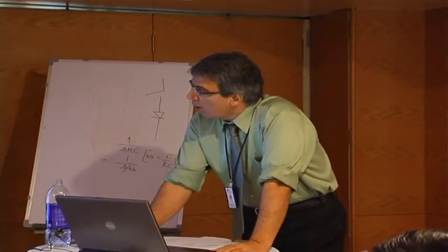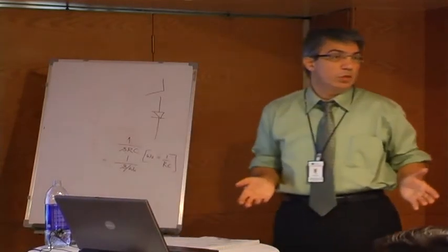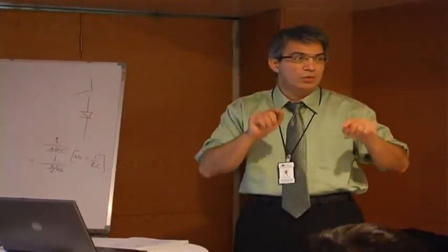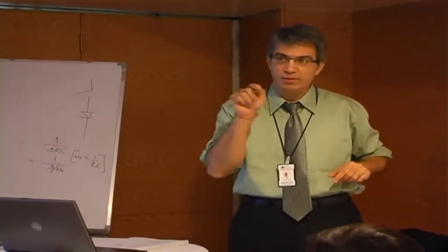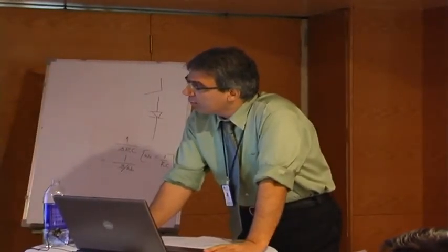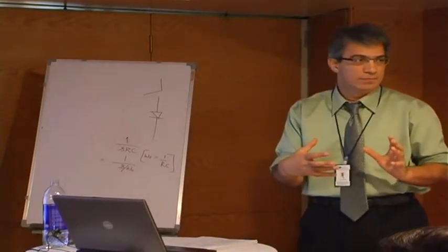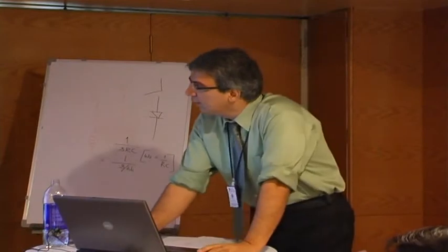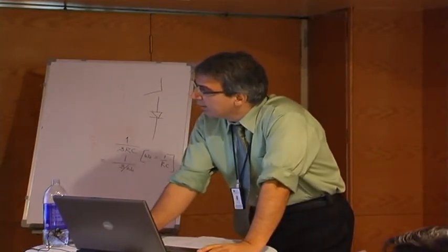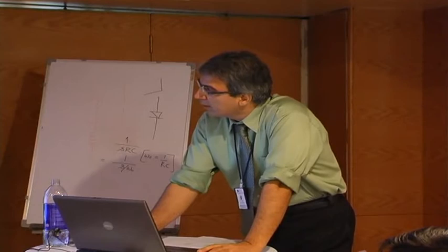And then for data collection, you can set all of them, say voltage, currents, power, and collect data on all nodes. Then you can also set it up so that you mark points and collect data only where the probe is. So you can say at markers only, which will dramatically reduce your data file. And then digital and noise.